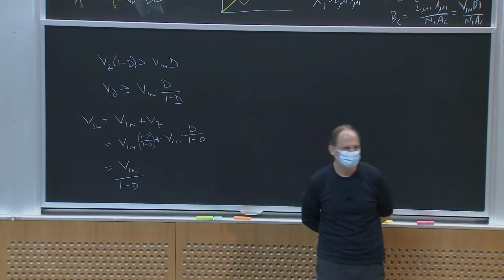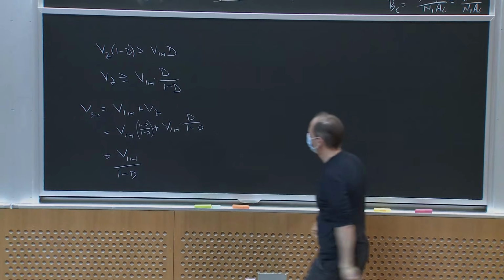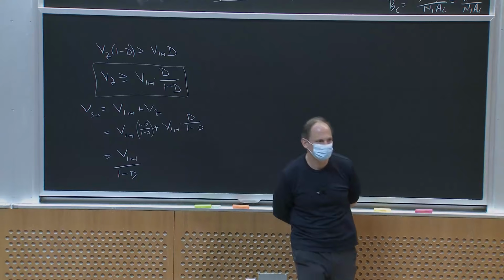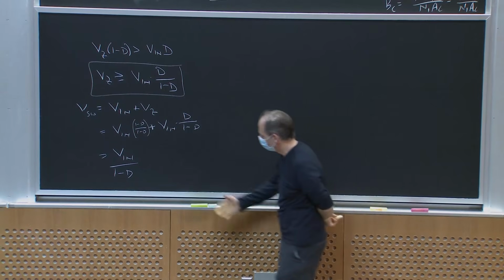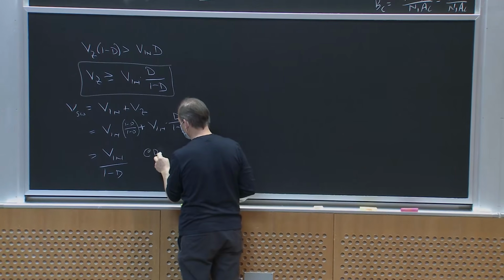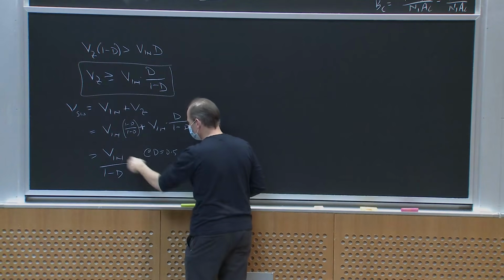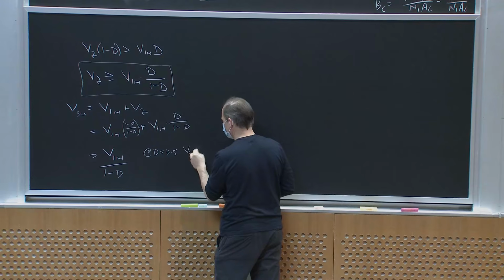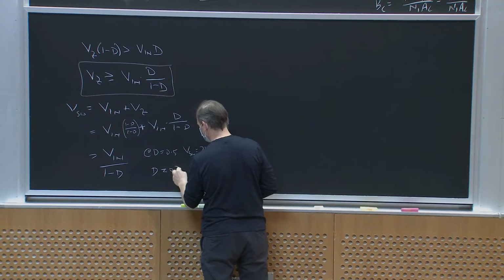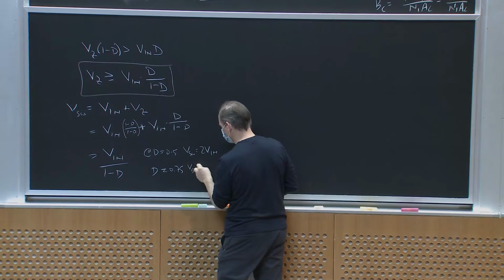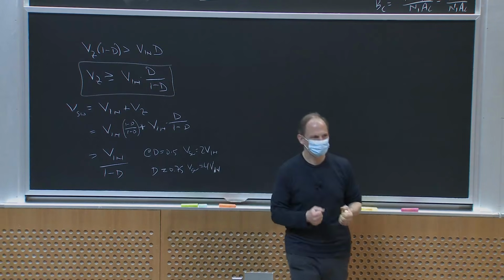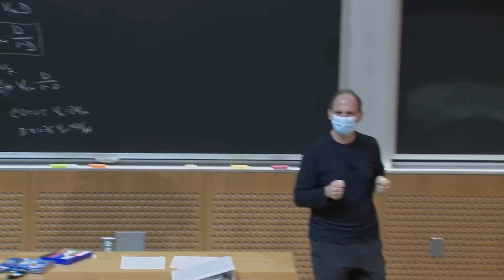So if I pick a big enough Zener voltage to get the zero volt-seconds balance on my transformer, I get this voltage. At d equal to 0.5, that gives V switch equal to 2 Vin. If I went up to a 75% duty ratio, V switch is equal to 4 Vin. That's getting kind of ugly. My switch voltage is considerably bigger than my input voltage.